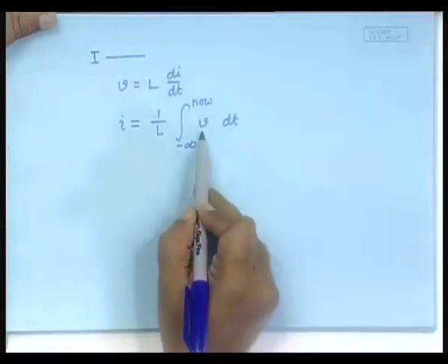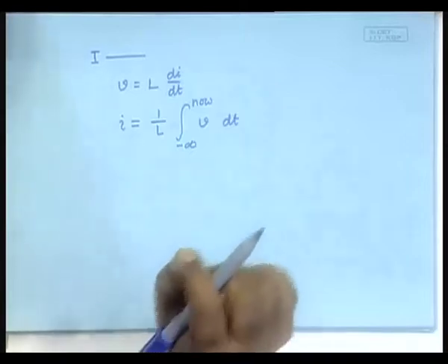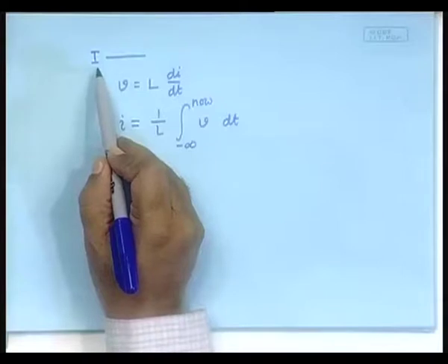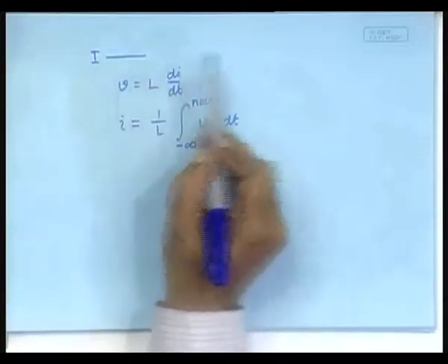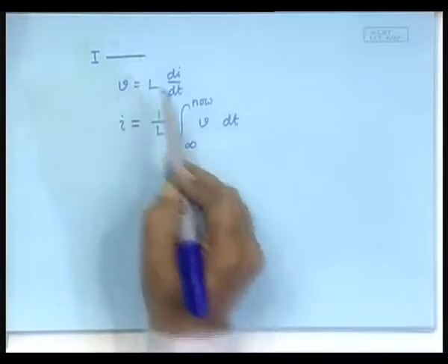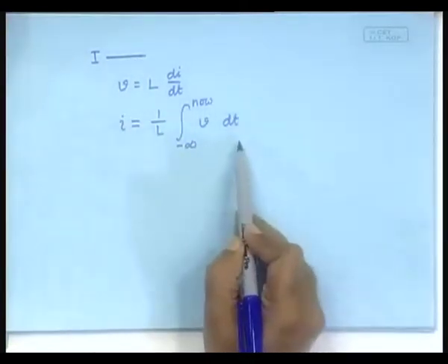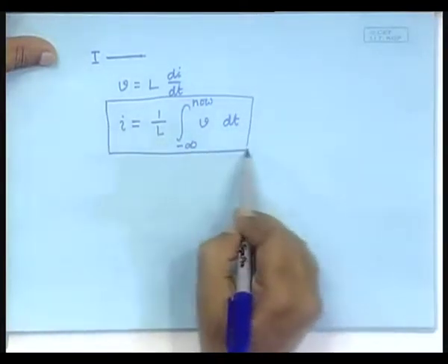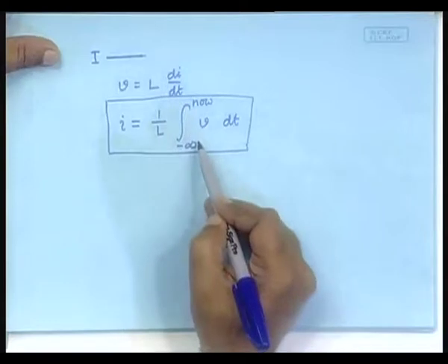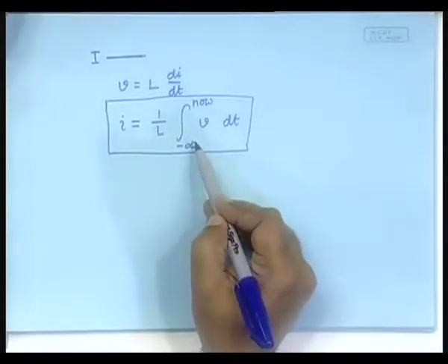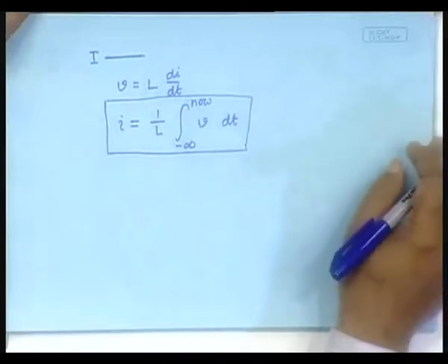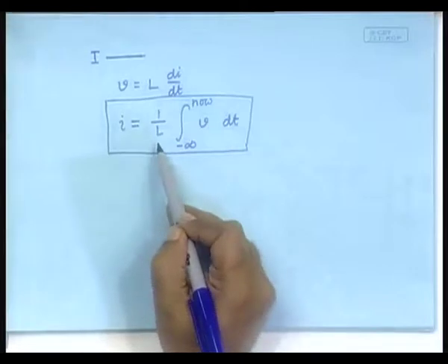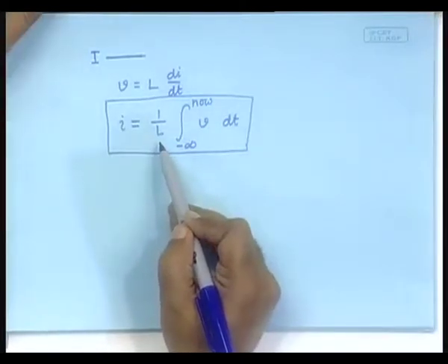So, effort integrated gives a flow, that is a special type of relationship which is a characteristic of the I element. Okay. The I element is connected with a bond with the rest of the circuit, and the moment we draw the bond we know that it has this character. So, this is the essential character of this. There is a reason why I am not using this as the essential character, but this. You will understand slowly when I come to that. So, in general, this is the character of the inductor or the linear inductor.